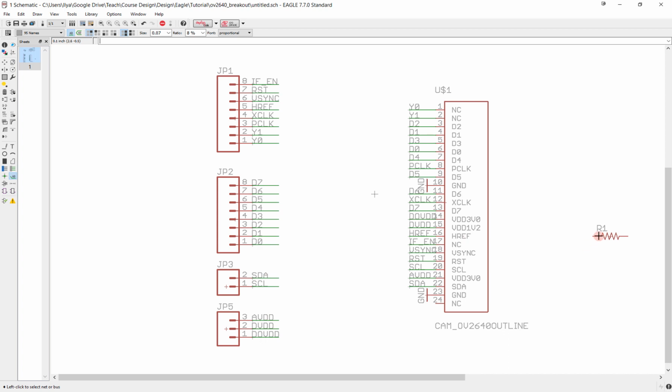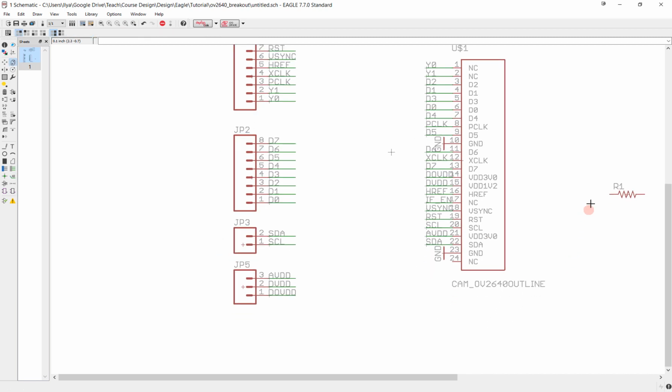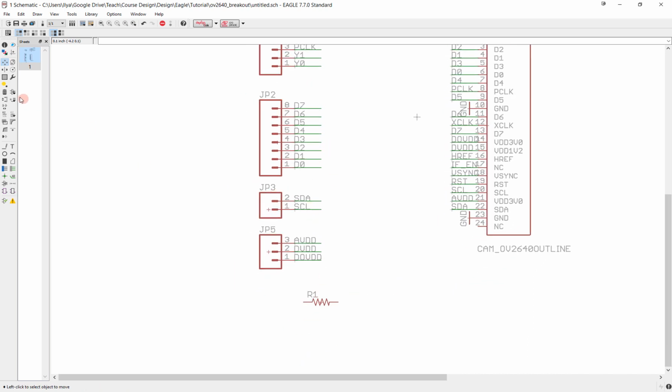And one more thing is now I could directly connect my resistors to the SDA and SCL pins, but just to keep them a bit separated here, and again just to emphasize the role of these nets instead of direct wire connections, I'm going to have them be separate, and so they're going to be right here, and I want to have a pull up on SCL and SDA.